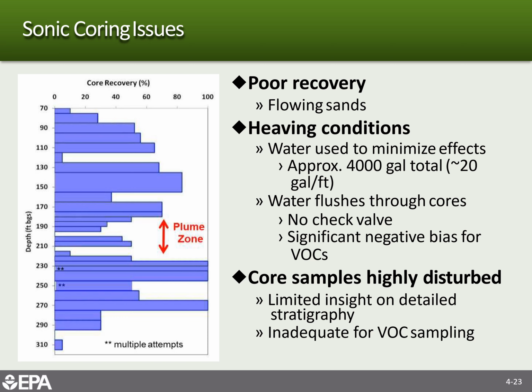So there are problems with some of this, because you're using this vibrating equipment to advance the casing, and sometimes it just disturbs the sediments. If the sediments have a very high amount of sand, it's more susceptible to disruption.